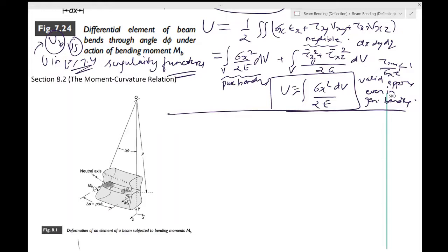Can we control the deflection due to bending? Just like we wanted to control or study the stresses due to bending, if this is the bending moment acting, what is the stress acting across the beam? Through that, at critical points we would find the state of stress under the combined action of bending, twisting, and axial loading. Then those states of stress would get converted to the principal values, and those principal values can be used in failure.